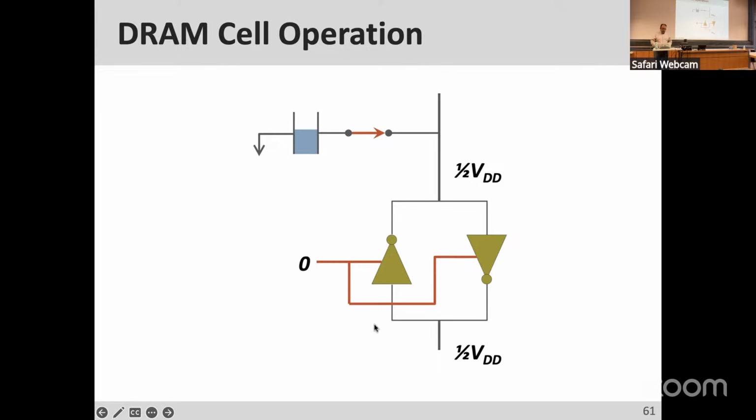At this moment, the sense amplifier is still disabled, that's why we have 0 here. The bitline is considered as a wire here, not connected to any power supply. It just has a capacitor because of the parasitic capacitance that each wire has.